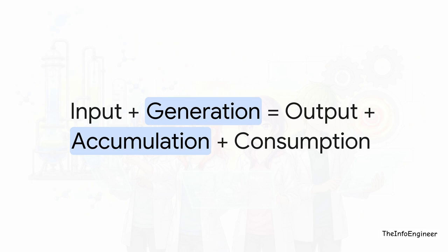And let me give you a beautiful shortcut. If your plant is running normally, it's at what we call steady state. At steady state, things like temperature and concentration aren't changing over time. And because of that, that messy, complicated accumulation term neatly drops to exactly 0.